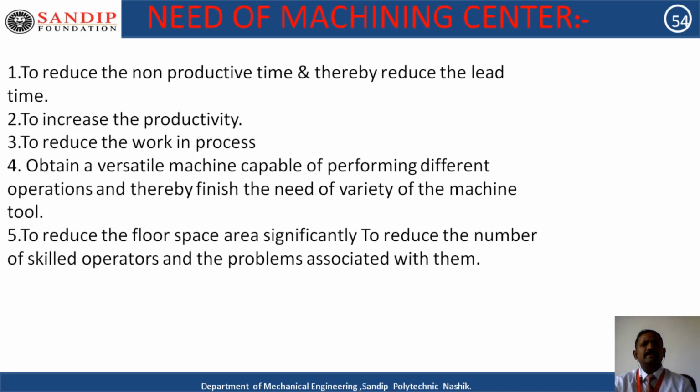Now, what exactly is the need of machining center? Sometimes a question may be asked. To reduce the non-productive time and thereby reduce the lead time, means whatever dwell time from one operation to another should be reduced. To increase productivity, to increase production, to reduce work in process, saving the time of measuring the coordinates on the respective surface also.